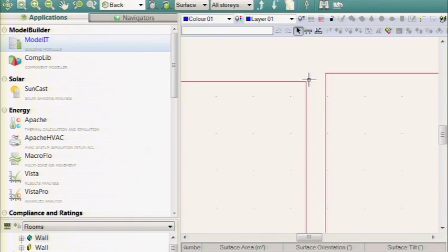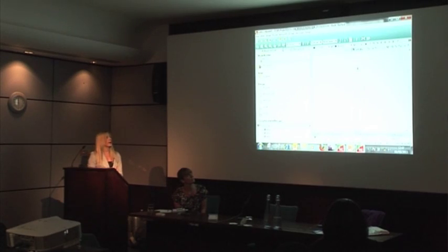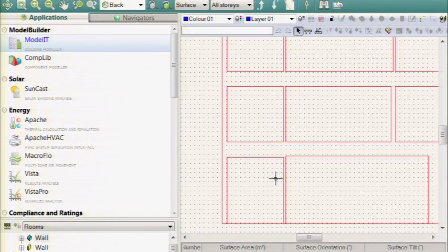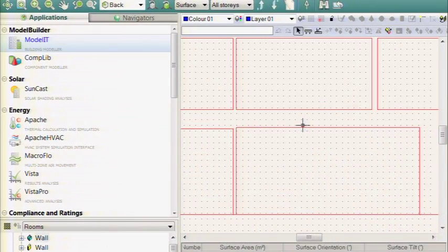And you probably know better than I do as engineers. So it'll depend on how bad it is. If they have overlapped a lot of frames and you end up with gaps and windows that are very off, then I would highly suggest redoing it. If it's off a little bit, you have to make that decision to see if it is going to work. But just make sure in that case they are accounting for the mullions on the curtain wall, and that they're drawing them in Revit, because then you will at least get a base of panes to start with. In this case, we could just simply draw a construction line and copy it over. So it's not a hard fix. It gives you a base to start with.